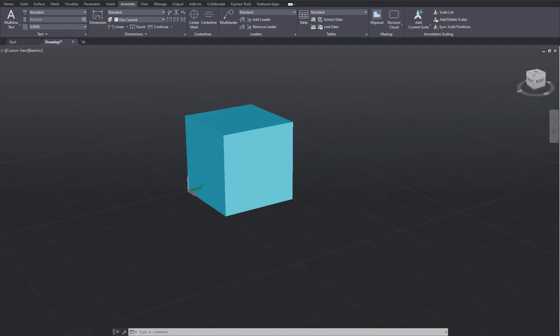Okay, so I just created this cube earlier. I changed the color by typing the color command and selecting cyan, and then I entered the box command. We typed literally box, and then I selected the cube option, and after that I simply clicked a 0,0 starting point, entered 1 and enter, and the cube came out.